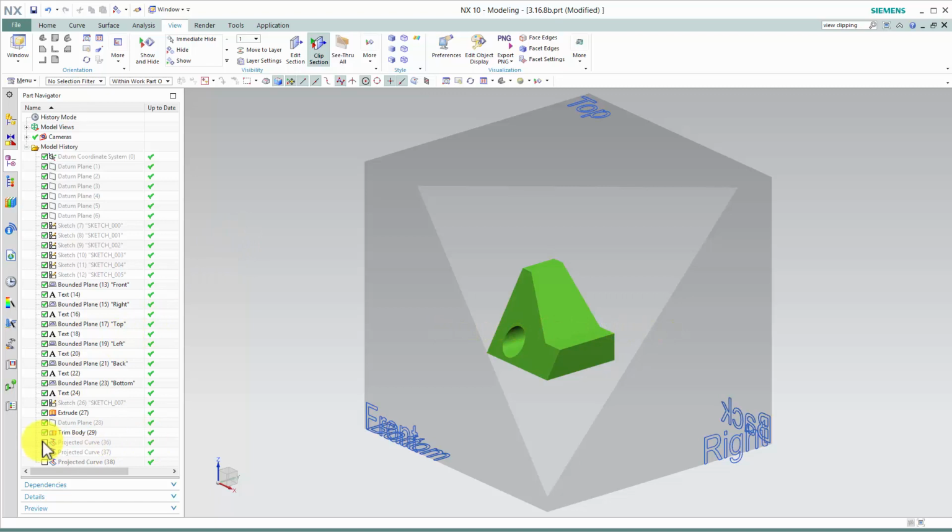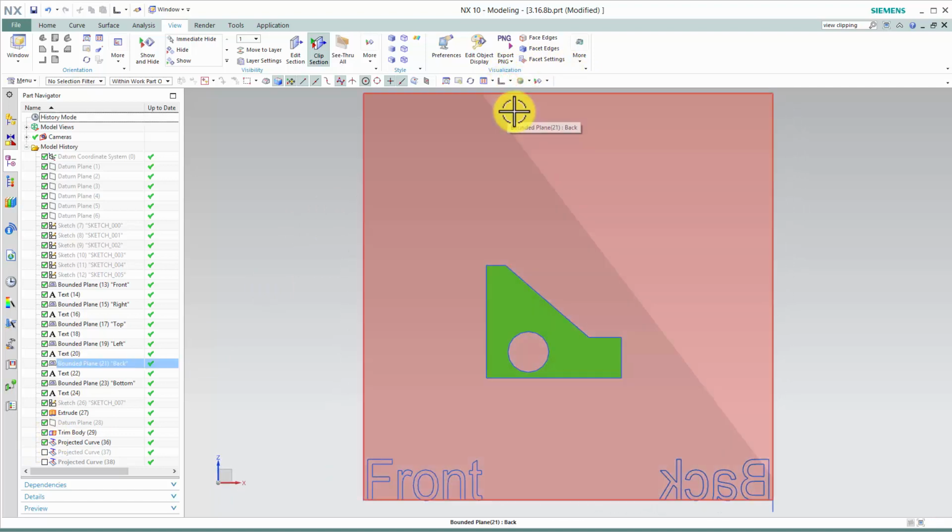All right, let's check to see if you have created the three correct orthographic views. The front orthographic view would look just like that. It's taking all of the silhouette outlines and just bringing them forward, normal, to the front orthographic plane.